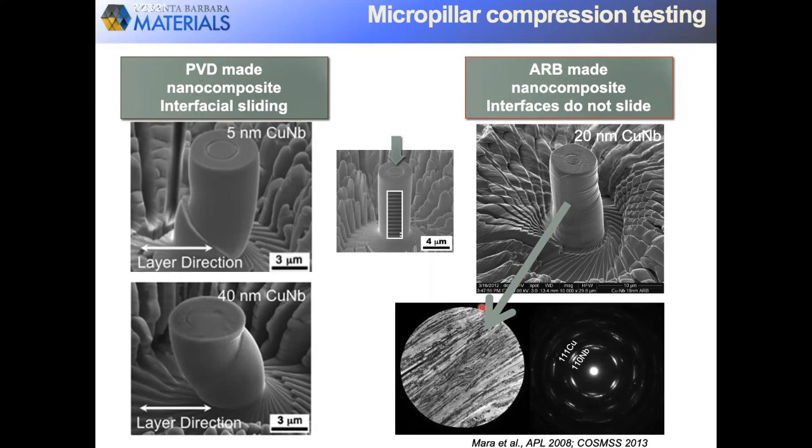So naturally, we questioned their stability to other types of mechanical deformation, such as compression parallel and normal to the layers. So here in micropillar compression, we found that the way it failed was non-catastrophic, and distributed shear bands formed and they crossed the layers.